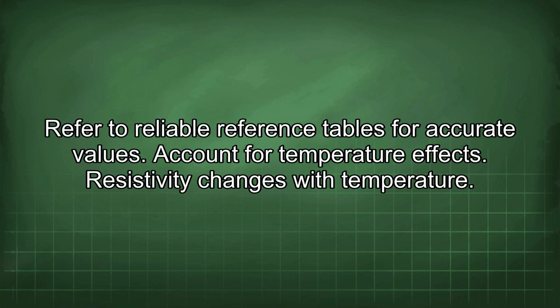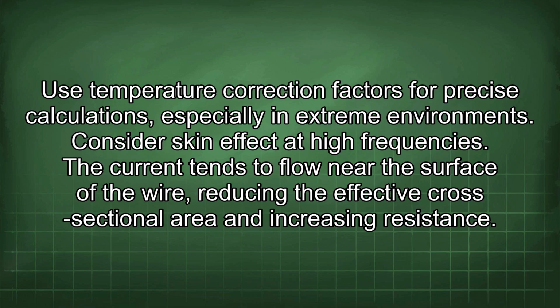Account for temperature effects. Resistivity changes with temperature. Use temperature correction factors for precise calculations, especially in extreme environments. Consider skin effect at high frequencies. The current tends to flow near the surface of the wire, reducing the effect of cross-sectional area and increasing resistance.